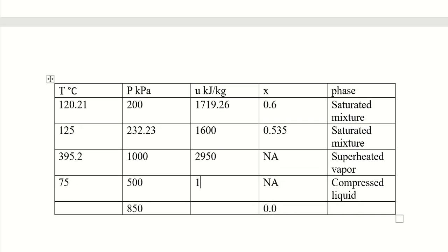And there was one. No. What was the internal energy? It was 313.99. And here we found our temperature is 172.94 and 731.00, and this is a saturated liquid.